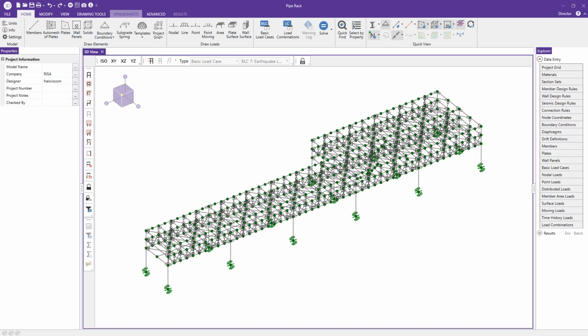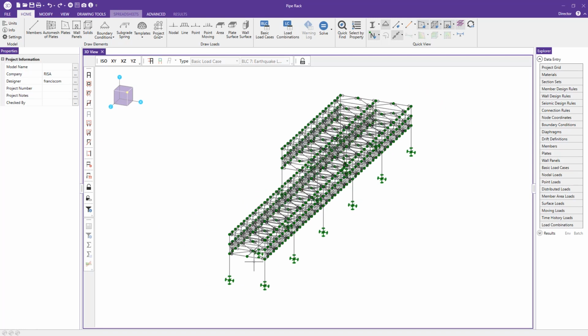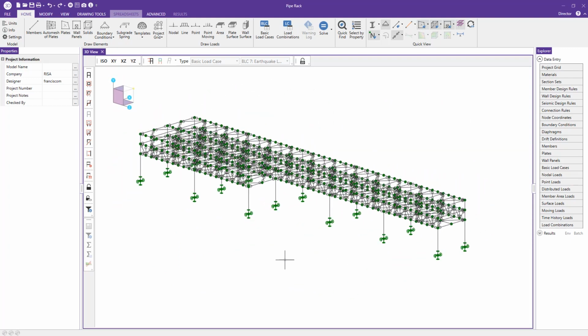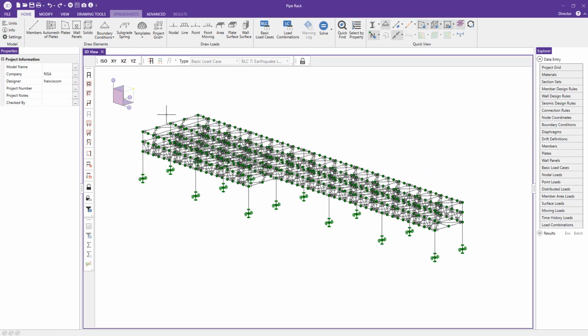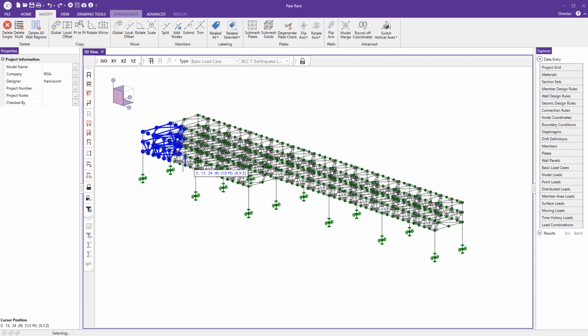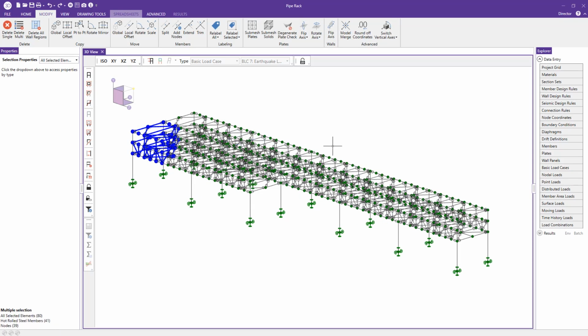Okay, now let's show you some different selection tools. We've naturally gone through this while working through these two models so far. You can do things like use our box to select. You can also grab different selections of elements on your project by holding Control while clicking and dragging. You can see there's a plus sign by my cursor now, meaning it's going to add to the selections you have.